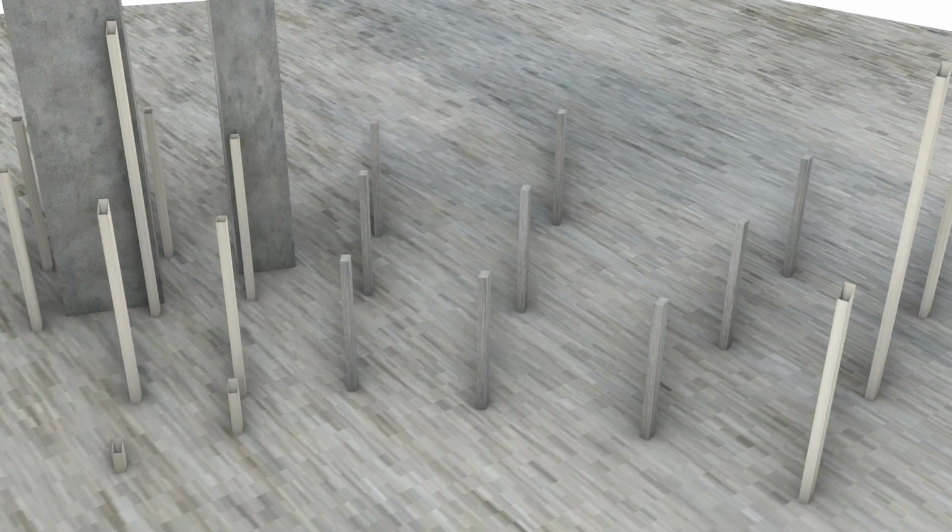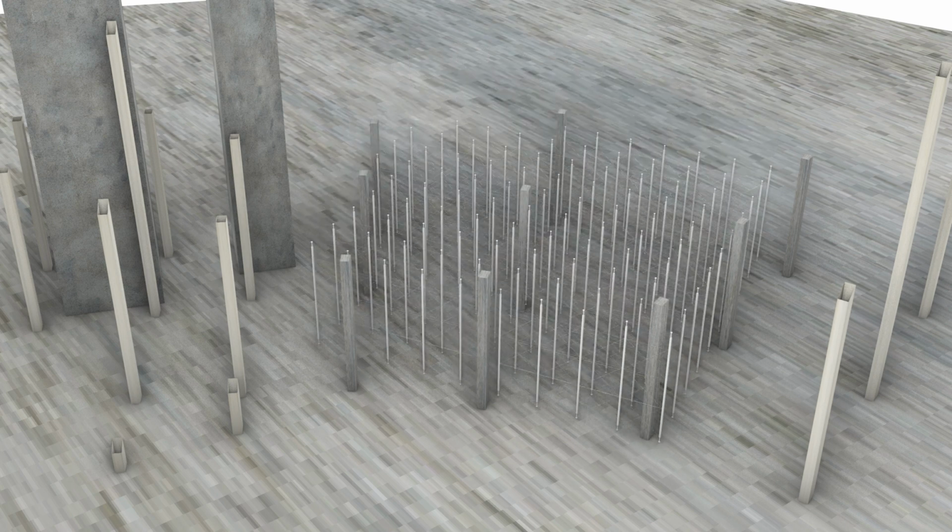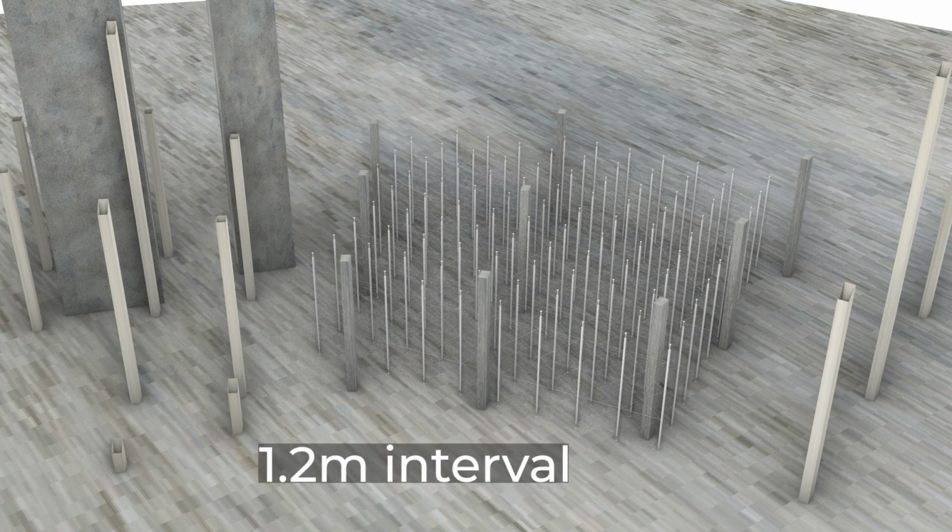After the mega columns, mat foundation and the reinforced concrete columns are completed, slabs of the stadium are constructed above them. These slabs average 305mm in thickness and carried a dead load of approximately 7.2 kilonewtons per square meter. To safely support this weight during curing, a temporary shoring system was installed first, consisting of galvanized steel pipes which are 48.6mm in diameter and 3.2mm thick, spaced every 1.2 meters.